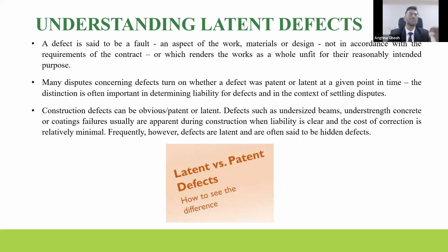So let's start. The first example which I can think upon is basement waterproofing leakages. This is, let's say, a very common latent defect which involves water infiltration into the basement and thus affecting the waterproofing works. Often this is due to the high porosity in the concrete or due to rising groundwater levels during certain seasons. Because this is not happening during the construction phase, why it doesn't happen? Let's say it is because there are dewatering techniques which are being utilized. Therefore, this is not usually detected during the construction phase, if at all there is some problem in the waterproofing.